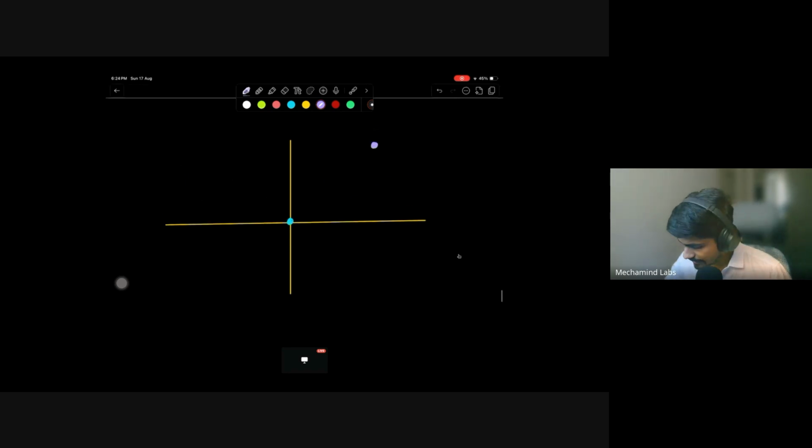Okay, now let's quickly look at the PID part, as to why I had kept the k linear and k angular values as 2 and 6. For example, if my turtle is moving at a very high speed, this is the turtle and this is the turtle which I have to catch. I know the angle that I have to turn by this much angle. But if my turtle is moving at a very high speed, it might happen that before turning to this angle, because the turtle turns slowly, I just overshoot this. Like my target got missed.